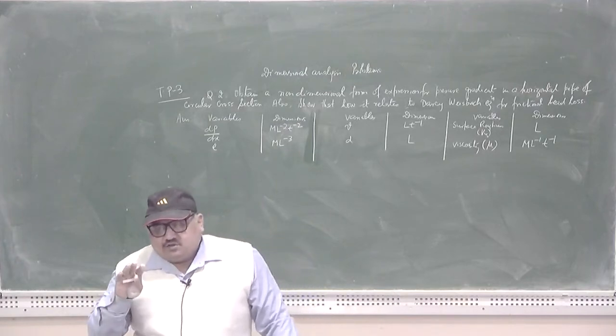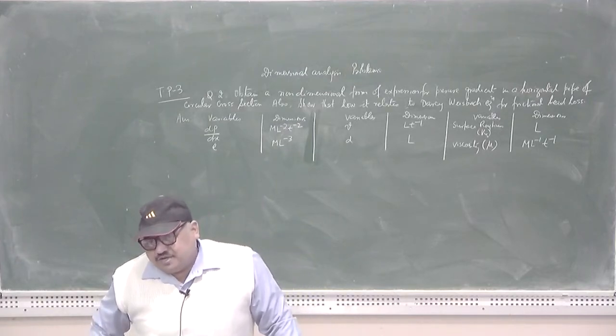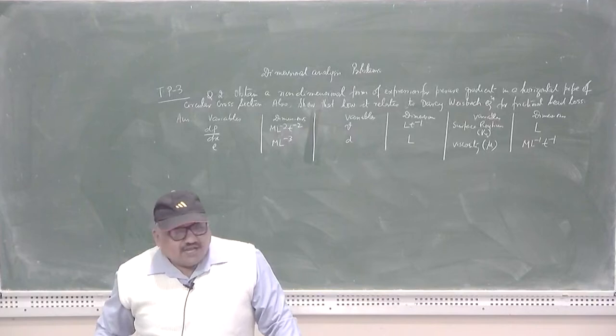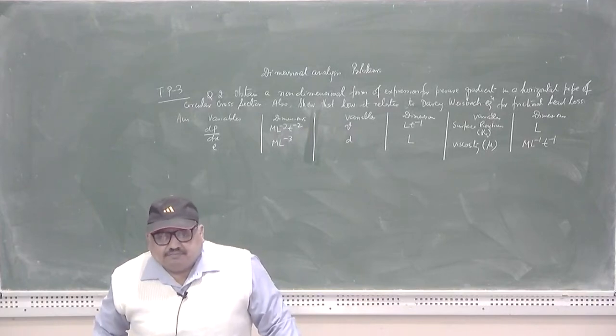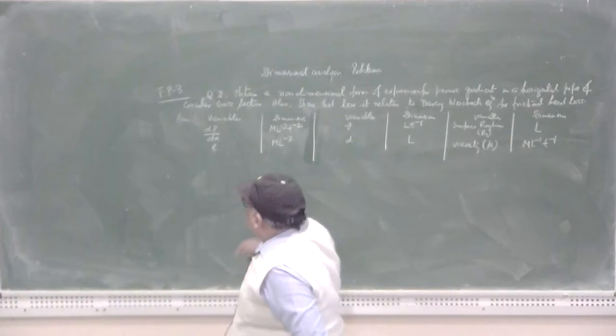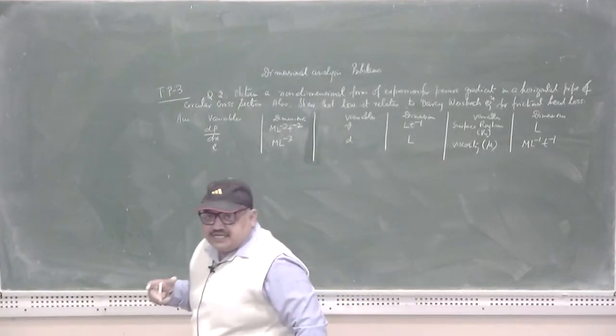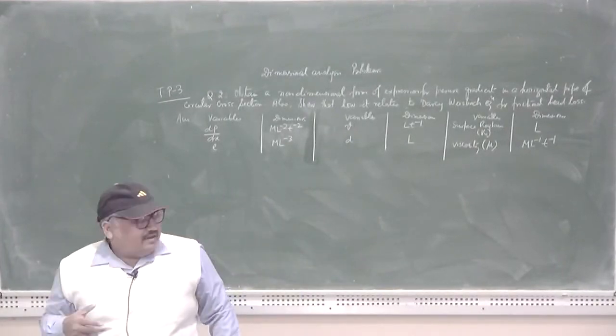So, the roughness gives rise to a reduction in the velocity, hence the reduction in the pressure and in the pressure head. So, the surface has a major role to play in such type of flow behavior.